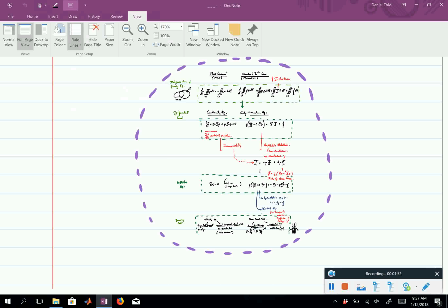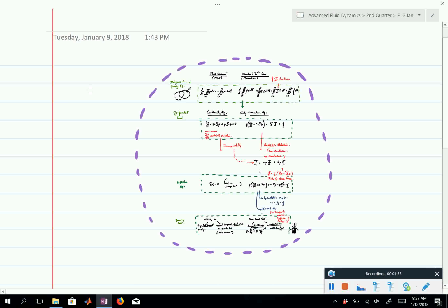So let me write that. Before going outside, you want to go through the filter of dimensional or scaling analysis. Now I didn't make a big distinction between dimensional analysis and scaling analysis. Dimensional analysis, you can always use the Buckingham-Pi theorem. But the Buckingham-Pi theorem applied completely randomly usually may not help you. A scaling analysis is when you start putting a bit of physical intuition about what are actually the relevant parameters.